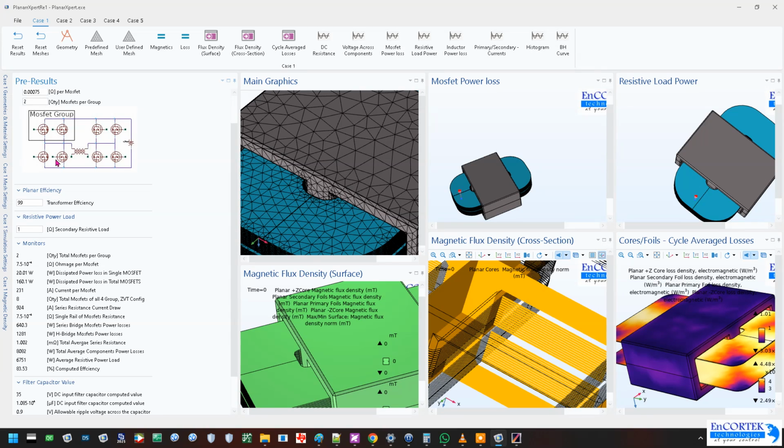We look at the datasheet for the MOSFET. If one MOSFET is exceeding, or two less, you put in more MOSFETs, so you mash up the MOSFETs, right? The total losses in the total MOSFET 160, that's all of these guys here, right? So we pretty much will mash up these MOSFETs because the current is overbearing for it. 8 MOSFETs we use in total.